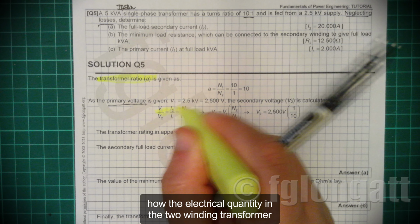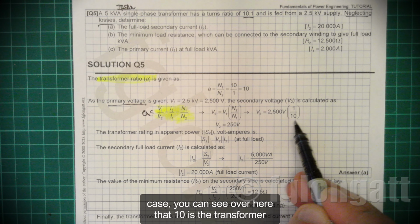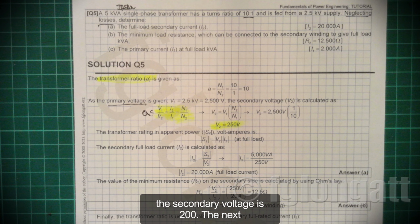The secondary voltage is the primary voltage divided by the transformer ratio. In this case, 10 is the transformer ratio. So it's simple to see that the secondary voltage is 250 volts.